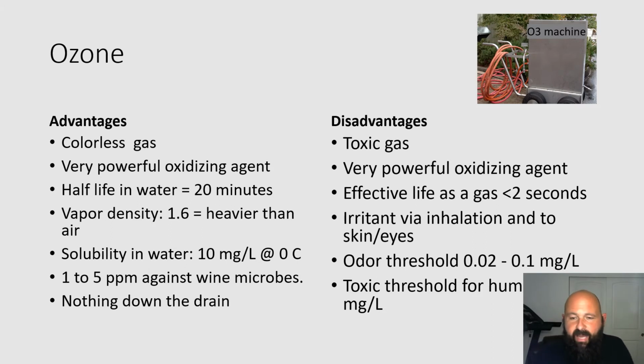And the downside, and one of the things you can't see with the screen in the way, is the odor threshold's about 0.02 to 0.1 milligrams per liter. And the toxic threshold to humans is less than a milligram per liter. So to get the strength high enough to be really effective against wine microbes, you're going to be starting to put a lot of pressure on the health and safety of your cellar staff. So while in theory it's a good idea, getting the concentrations at reasonable levels to be the end-all, be-all sanitizer for your cellar is probably going to be pretty difficult to do.